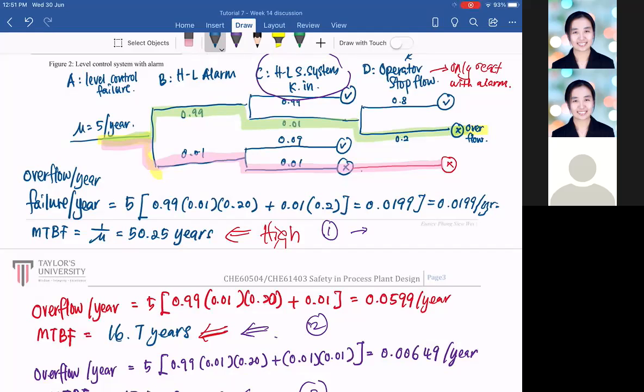Like when it hits the STEL level, there's only 15 minutes exposure with a 1 hour break, and then go back for a 15 minute exposure, etc. So that basically talks about lots of calculations in chapters 2 and 3, talking about the probit equations, like death rate. Let's say people are being exposed, there's a gas leaking, for example, for a duration of 2 hours, and that's the concentration.